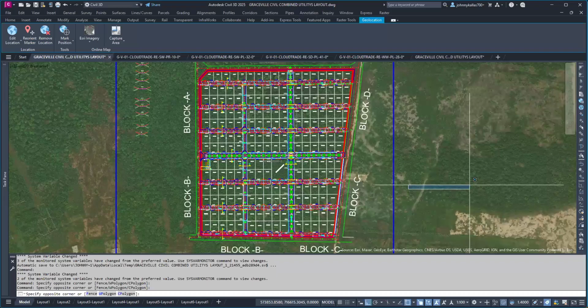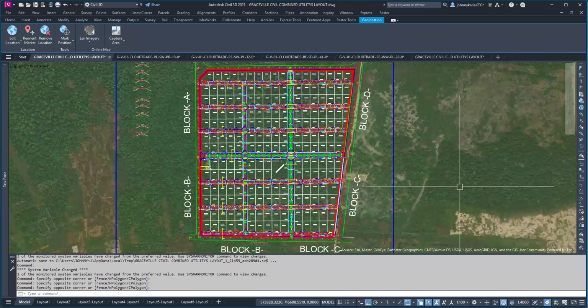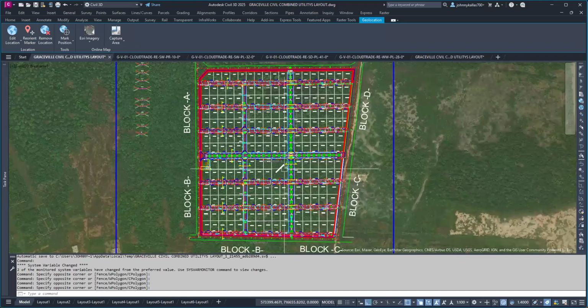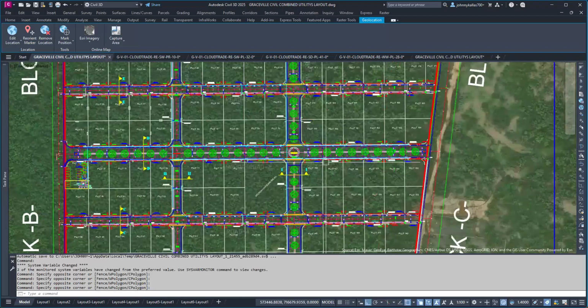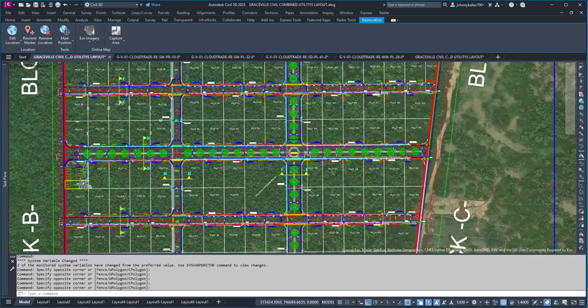It talks about the behavioral aspect of the soil. Sorry, ma'am, as in soil test, you mean? Yes, something like that. I fully understand your question. For the road, at the beginning, we are going to do clearing, like 50 cm, to remove the clay and the mold. And we will backfill it, so we will be sure our road, after we backfill it with the dredger, will not have settlement.